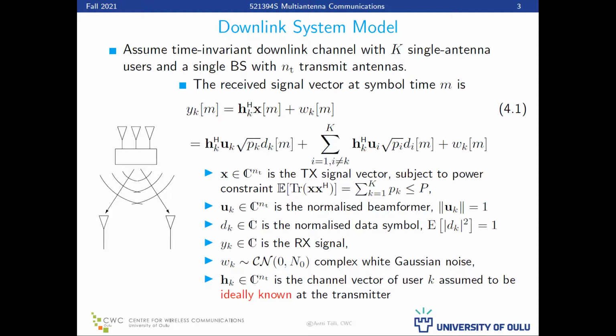Meaning that in a TDD case, you can assume the fading is slow enough that you estimate the channel from the uplink pilots, and then design these decoders based on these uplink estimates, and we assume the channel stays more or less constant. Well, here we assume it's exactly constant. Then we apply these designed decoders for the downlink transmit.